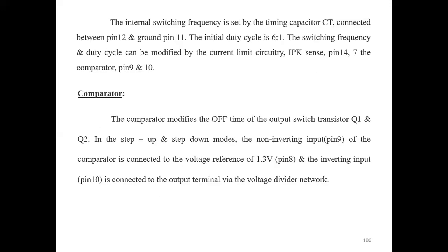So the comparator modifies the off time of the output switch transistors Q1 and Q2 in the step up and step down modes. And the inverting input is connected to the output terminal via the voltage divider.